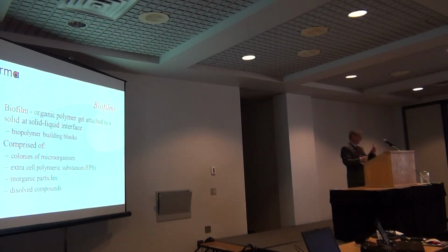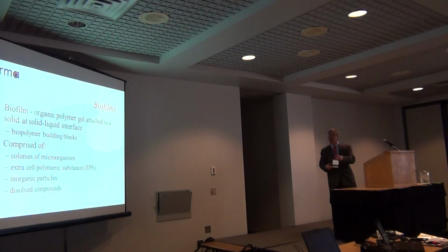Most people are very familiar with suspended growth systems. Has anybody had any experience running fixed film or biofilm systems? Not too many. Biofilm is another term for fixed film. If you left a tennis ball or something floating in a bird bath for a couple of days or a week, and you picked it up, that slime layer underneath is a biofilm. It's really just organic polymer gel that attaches itself to a solid-liquid interface. What these biofilm reactors do is put a media in there and run the wastewater over it and develop a biofilm, so that the bacteria, unlike in the activated sludge system, aren't suspended, but are fixed in this media.